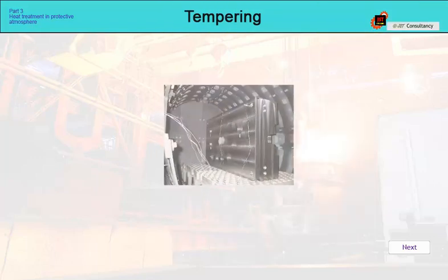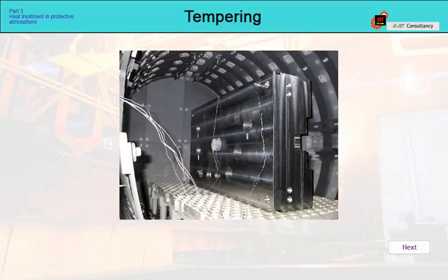In practice, the permissible delay time between quenching and first tempering is a widely discussed question. The general rule is that this time should be as short as possible, for example, within 2 hours. However, there is no complete agreement on this parameter, and opinions differ.